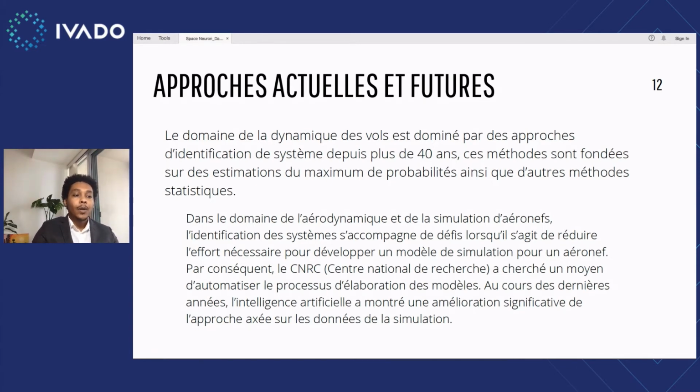We are here to bring a new way of combining traditional system identification and machine learning to build reliable, robust, useful models that could build the aerodynamic model for us purely from data, with a little bit of system identification, which is understanding the physics of the problem, as a pre-step to the AI model building.